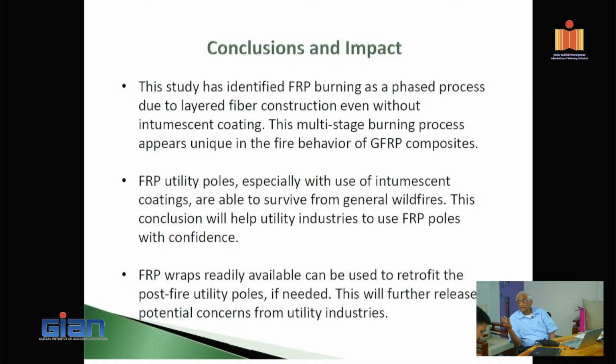So each layer is 1/160 inch thick. All I'm saying is 1/160 inch thickness takes 10 seconds to burn through. Now your 1/4 inch bar will take roughly 30 minutes. That is without the concrete cover. With the concrete cover, you get a better value. Okay, so that gives you a quick presentation on fire.